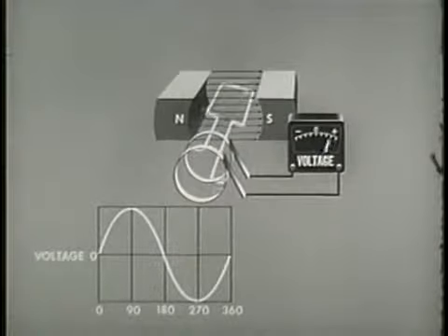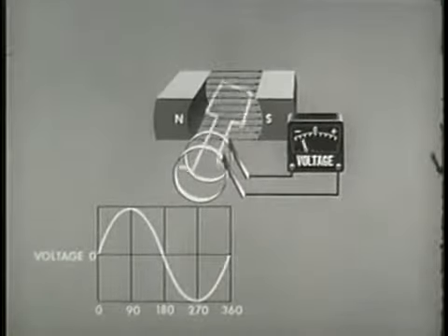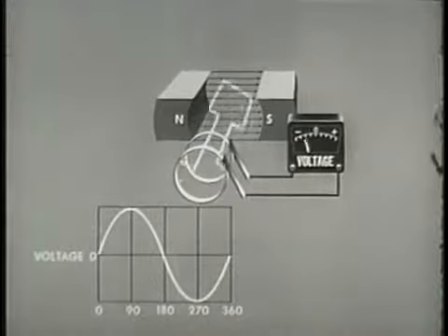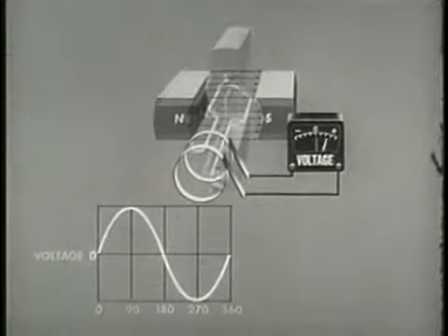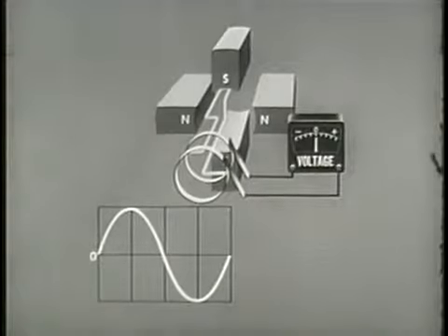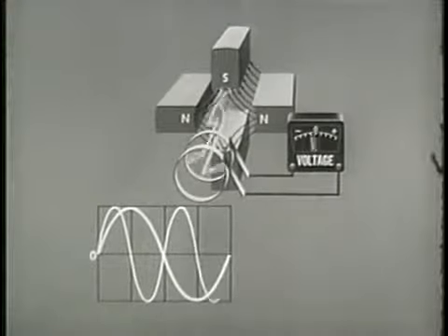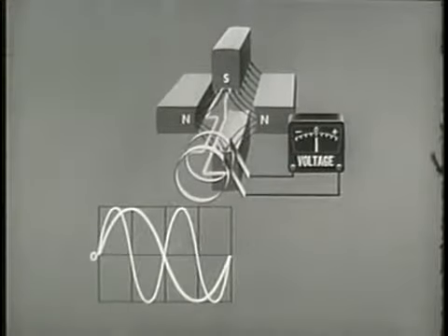In this example, the two-pole machine used has one magnetic field. As the armature makes one revolution, one magnetic field is traversed. Adding another pair of poles adds another magnetic field. Now there are two magnetic fields. The armature moves through one field in half a revolution.